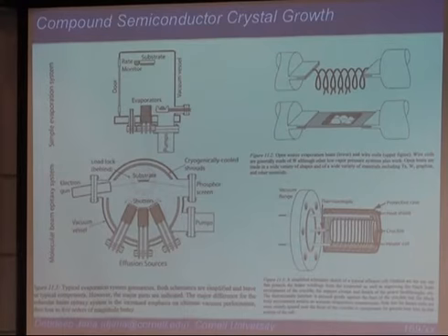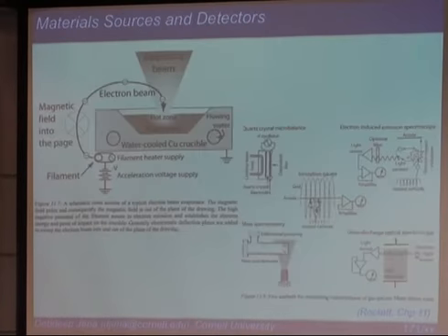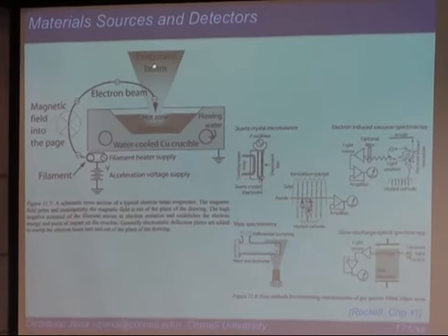It doesn't fluctuate too much. But the E-beam, I think, you know that current has always some noise. The shot noise is also because of discreteness of electron charge, and many other things. There's some fluctuation of current with time, and therefore the E-beam flux actually is not very precisely controlled. It is reasonably precisely controlled, but there's some fluctuation. If your growth is very sensitive to the flux, then you have to work very hard to control it.